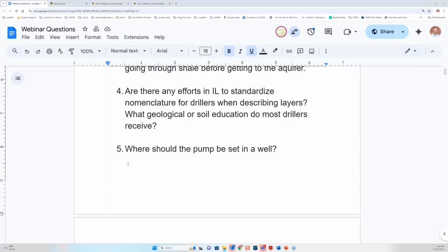That's a case-by-case thing. The main rules are you need to test pump the well so you know how much drawdown there's going to be. You want to make sure your pump, if it's a submersible pump in the well, is below where it's likely that the water levels are going to drop. You don't want the pump to be above the water. In most cases, they're water cooled. And also if the water level reaches the suction of the intake, the pump can start sucking air, and that causes problems in your lines and all that stuff.